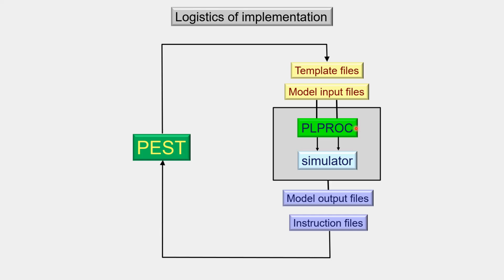PLPROC stands for Parameter List Processor. So PEST then has to write input files for PLPROC using template files. PLPROC writes input files for the model. And in doing so, it attempts to maintain that same non-intrusive interface with the model that PEST uses. PLPROC actually uses template files to write model input files.